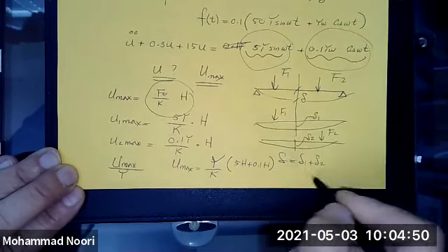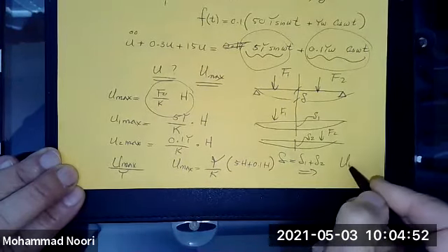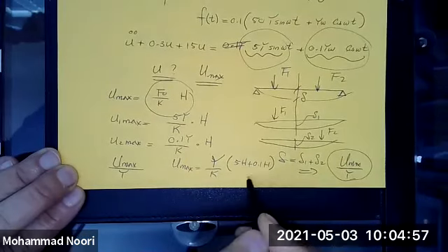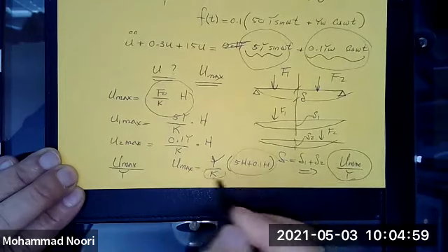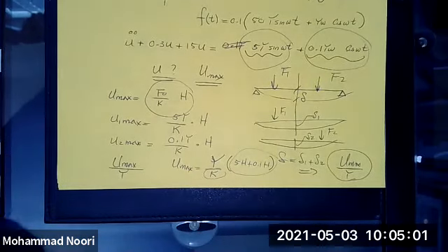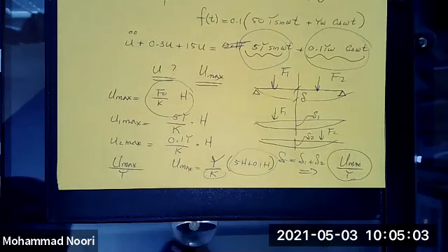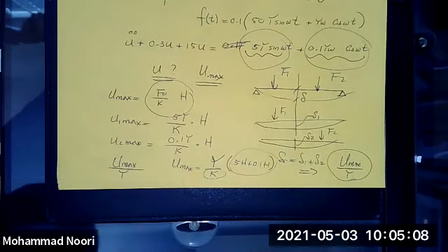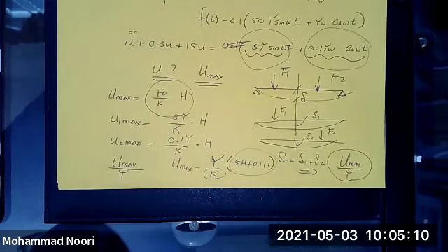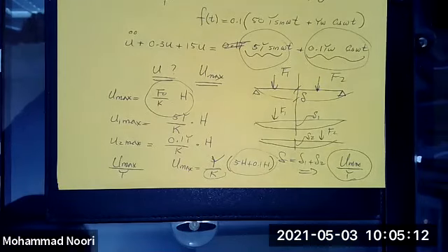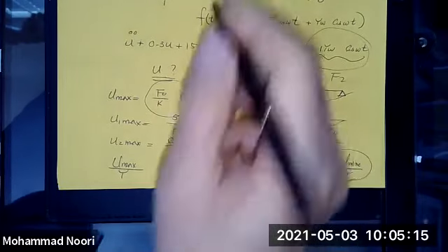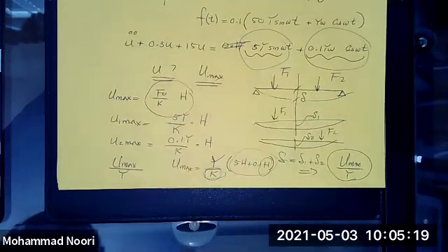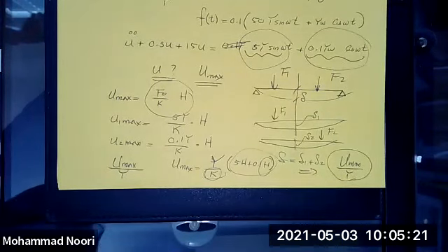So you can easily find the ratio of U max over Y, which would be simply a function of H and K. I'm going to stop here because you know what, of course, H is. H is 1 over the square root of (1 minus R squared) squared plus 4 zeta squared R squared. Okay, so you can substitute for H given these values. You have K, which is the total stiffness of the system, and you can find that.